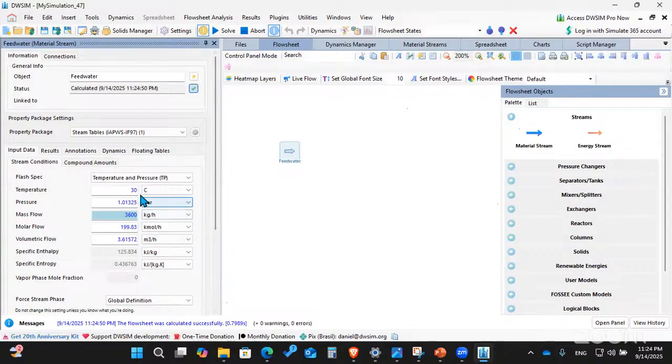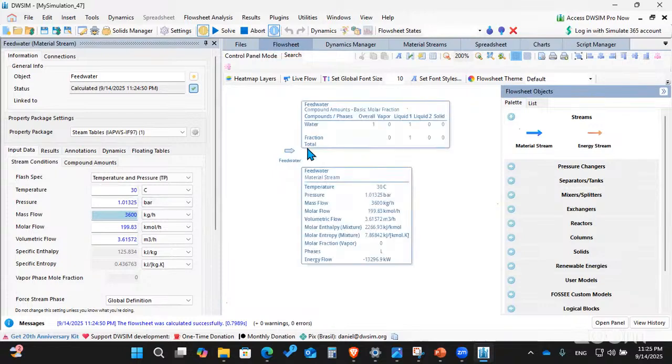And of course, remember on your PFD, you have a pump, and the pump will be taking the water at atmospheric pressure, because it's not being pumped yet. The flow rate will be 1 kilogram per second, which is 3,600 kilograms per hour. So we leave it like that. This is the flow rate we want, we don't want it to be very high. So we have defined our feed water.